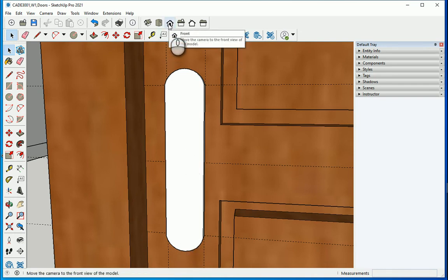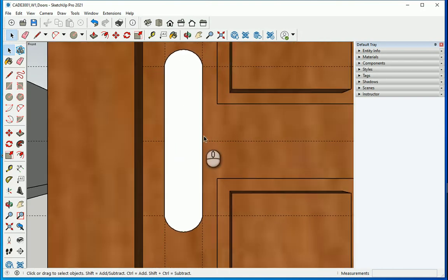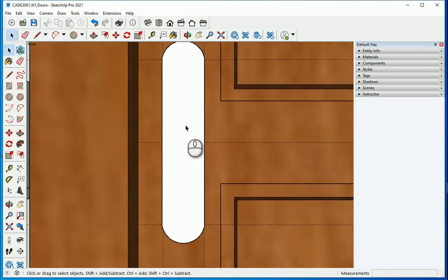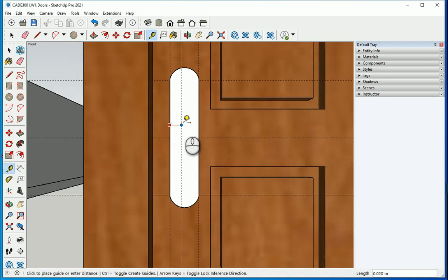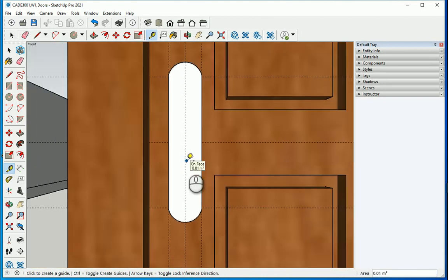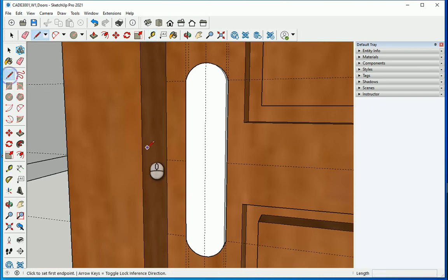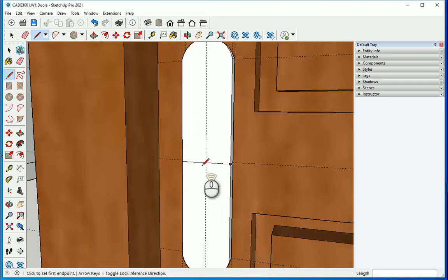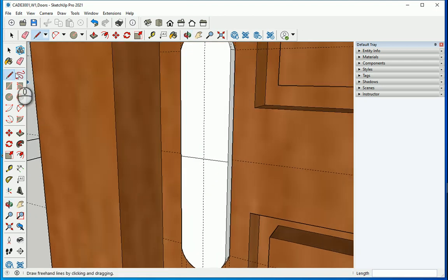I'm gonna go back to front view. It's better like this. And I want to consider a center point around here. So how about I go with T, tape measure, and if I hover the mouse around here, this is giving me the center location. I also want to just draw one line or L around here so we know that this is actually the center, right? Now, next thing I'm going to do is that I want to use tape measure T,